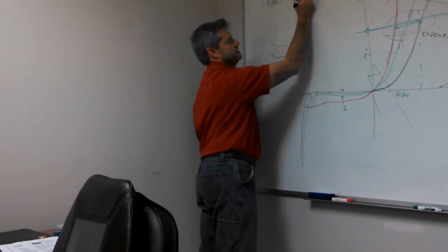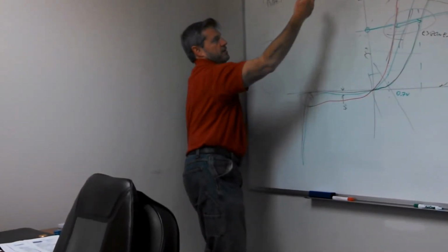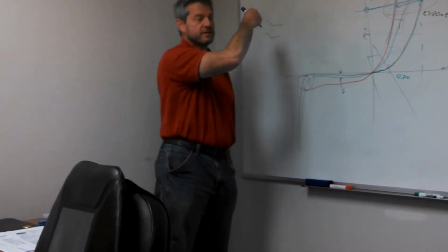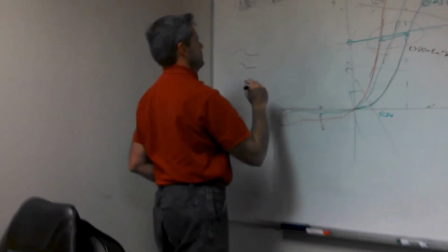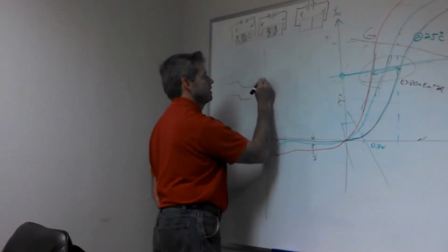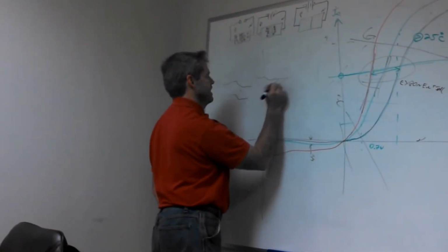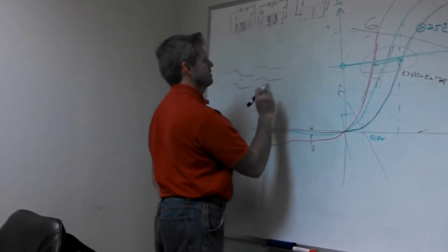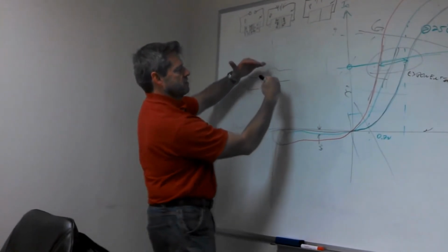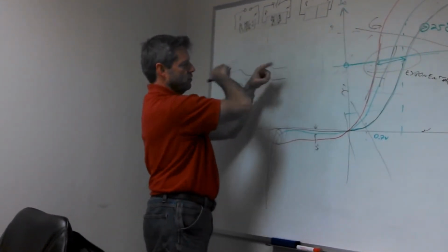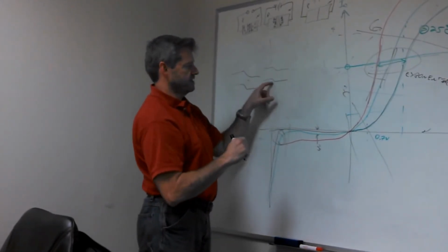Those are E's. And my electrons are going to be bunching up here because they're going to be repulsed by the charge coming in. So I'm narrowing this junction, which in the band diagram, I believe, flattens it out. I'm horrible with band diagrams. So this becomes closer to level, so that electrons and holes can just flow their different ways without having any obstruction in them.